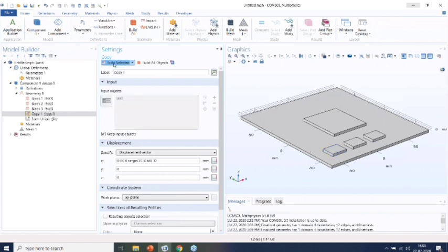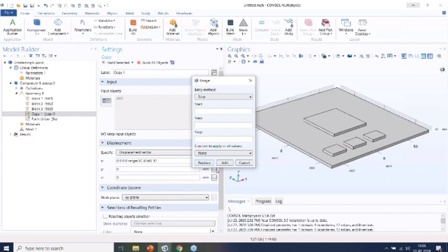So even if I build it here, you will see that just the 2 ICs are provided over here. I did not get anything created in the Y direction at all. So in this case, what I need to provide is the Y directional displacement as well. In the Y directional displacement vector, I am going to provide, start with range as 25, step size is 25, and it should stop at 100.